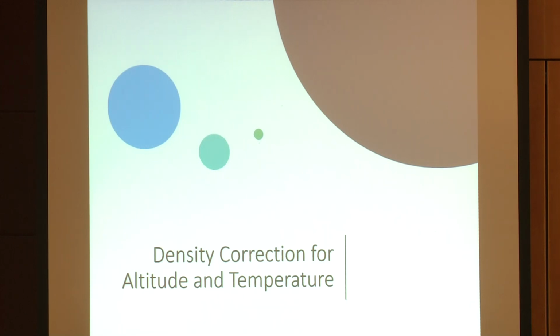So what I like to say is that the airside TAB work is very challenging for most technicians. And usually what we do is we have a TAB technician that's certified, but we always put a helper with them. It's such hard work to do by yourself, and you really need somebody helping you haul around the ladders and hold the hood and do the pitot readings and this, that, and the other.